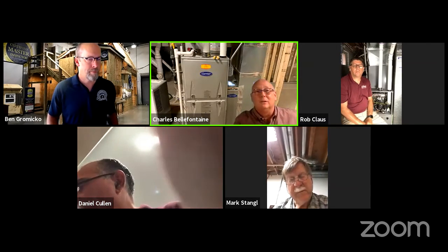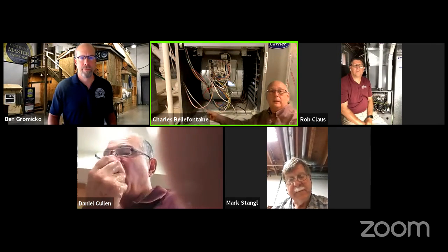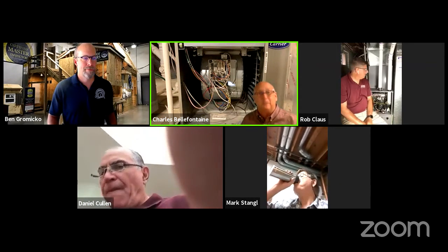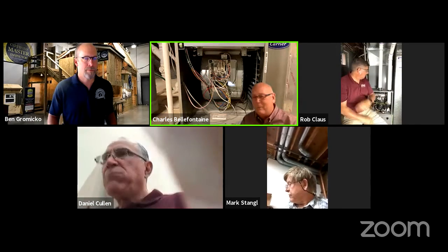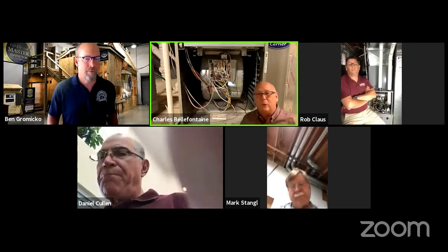So one of the first things that I'm going to look at is down underneath in the blower fan. So if you can get under this area here and shine a flashlight on there, that should be dry. Now, this isn't going to be a telltale sign that there's a hole or a crack in the heat exchanger, but if there's rust, condensation, or anything else there, it shouldn't be there. So it could come from the humidifier overflowing. It could come from the air conditioning overflowing.